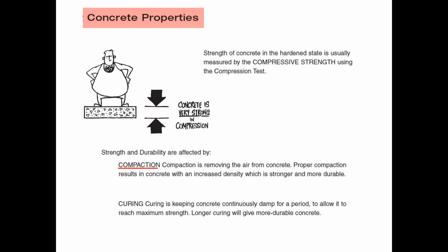And also, which we're going to go into a bit more detail as well, curing. So curing is keeping the concrete continuously damp for a long period, and that helps it cure and get its strength.